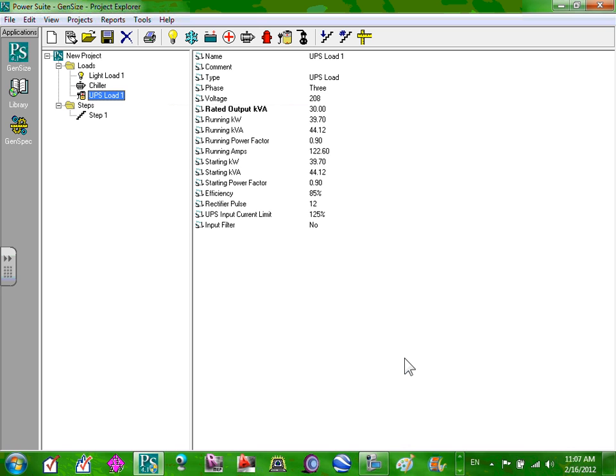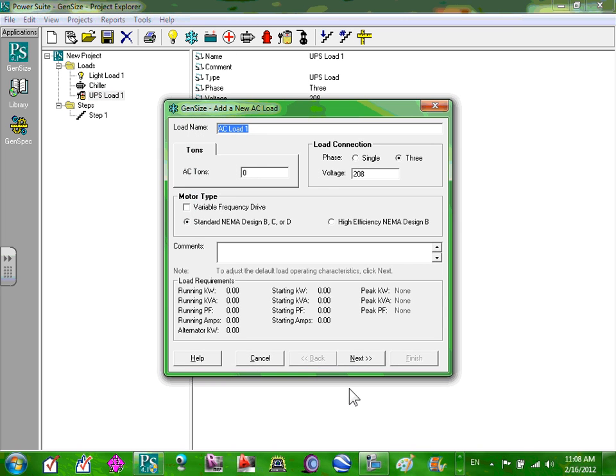And I told them, Jerry, to keep the default unless you know otherwise. When we do the loads, you've been doing the same thing. You keep the default in terms of power factor and so forth, unless you know otherwise. Yes. Very safe way. The defaults will keep you out of trouble, because if you go too lightly loaded, you could undersize things, which is a bad thing.